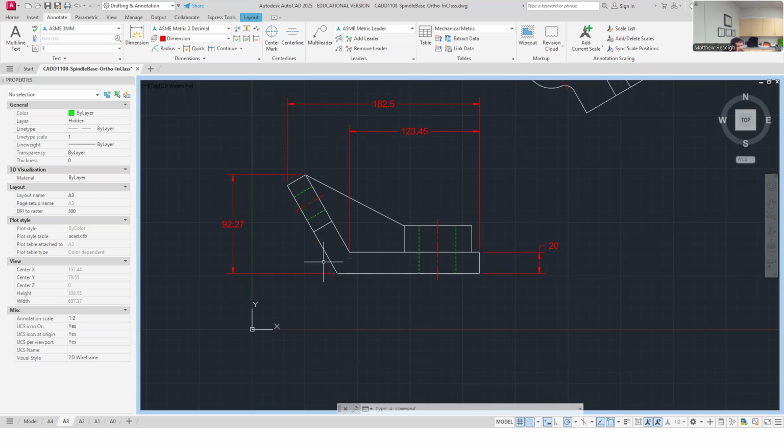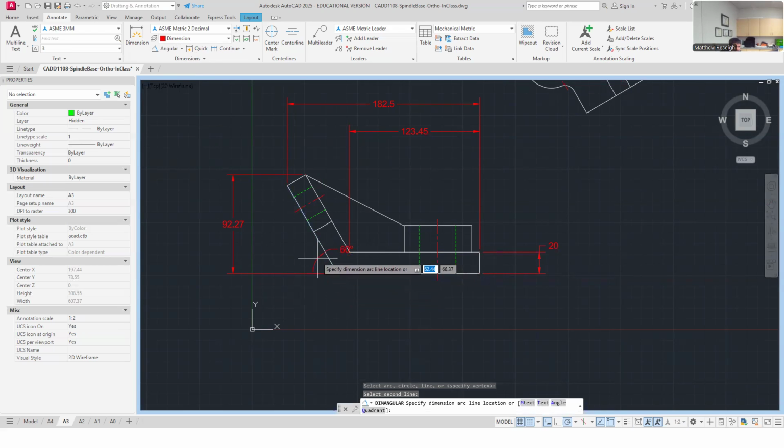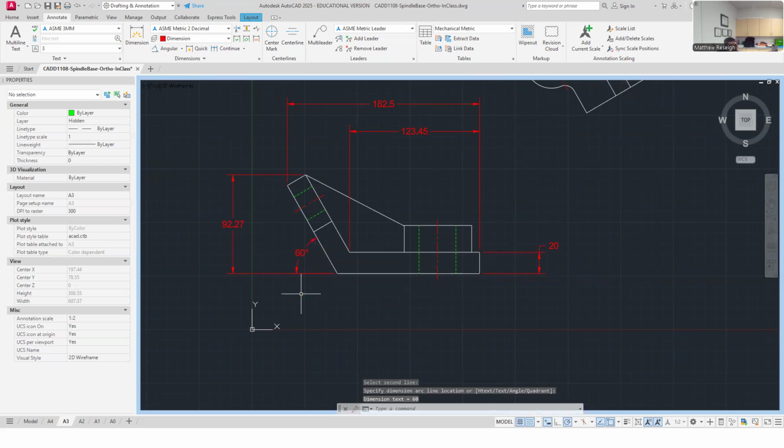And so you could just put an angle on here. I feel like that's more of a reference dimension, and it's nice to know that the relationship of this to that is an angular bent up. ASME would like us to maybe use this minimally, but I still use it. We're talking about from here to here, right? The relationship of these two parts is 60 degrees. I'm going to drop that in there, but I'm going to call it a reference dimension probably.